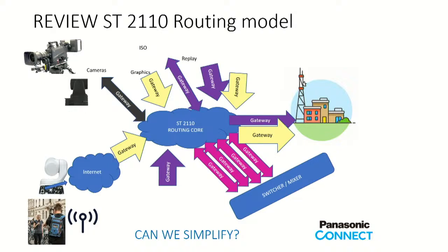For example, our Panasonic cameras now have an SFP built directly into, say, the PTZ. And you can take the network straight out of it, ST2110, and route that video without any requirement of a plug-in or BNC or anything else.